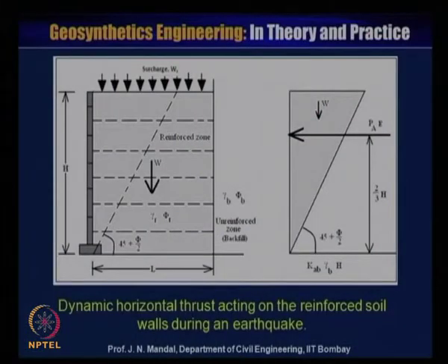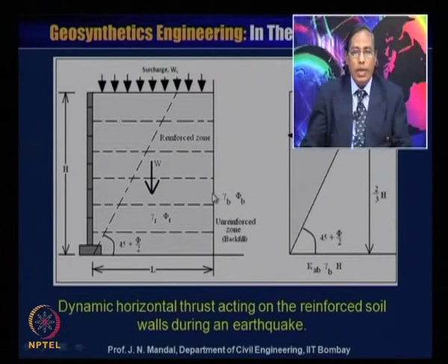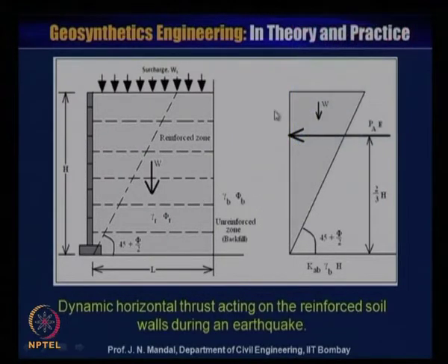So, this is the reinforced soil wall. As usual, there is a surcharge load. This is the length, this is the height of the wall. This is the dynamic horizontal thrust which acts on the reinforced soil wall during an earthquake. Here the distribution is slightly different; it is inverse, increasing like this.